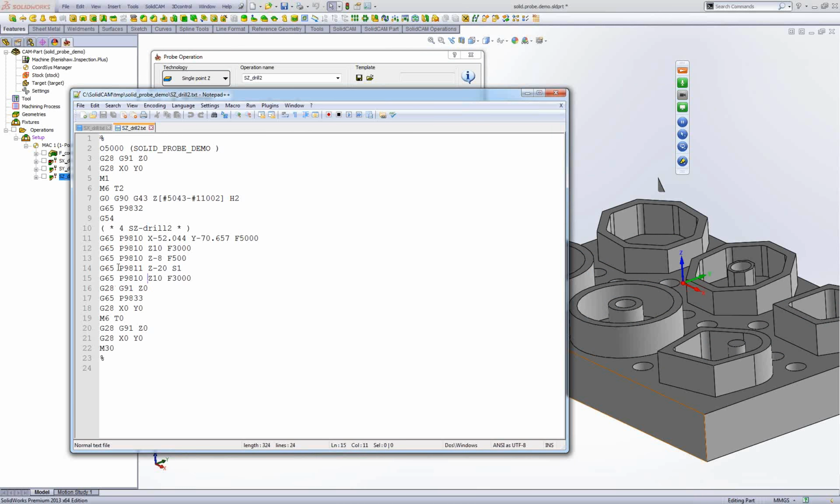Yes, you see measurement cycles. Z on this touching point is minus 20 and store to home number 1 in the tool table. That's meaning G54. Reference, switch off the probe and even send the probe device to the magazine. Don't leave it on in the spindle.